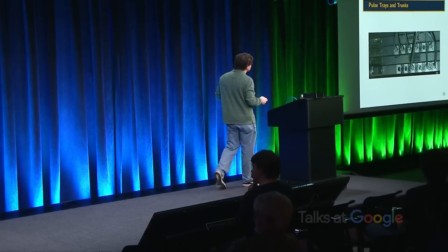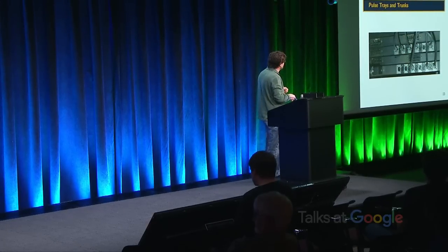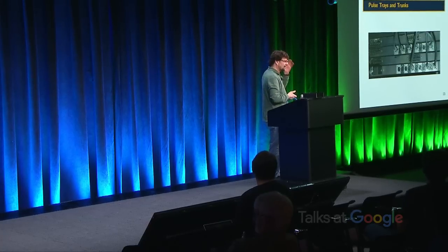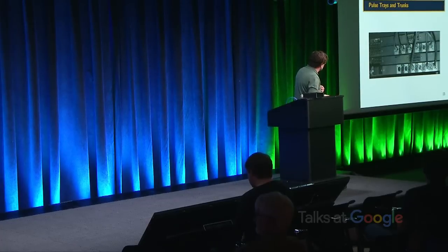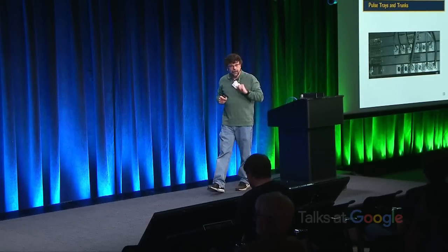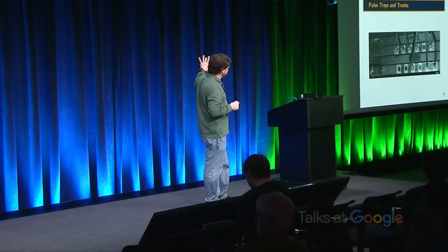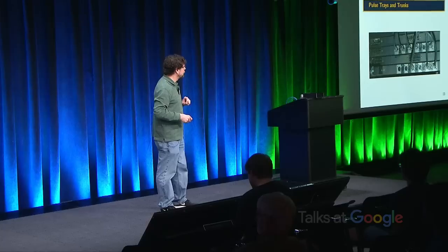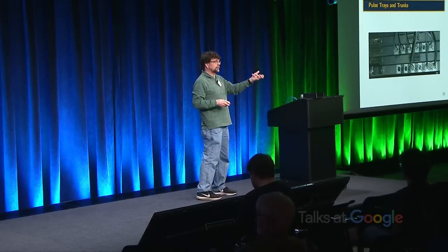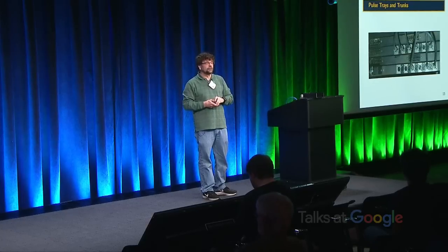And one of the things that is kind of inaccurate is the mixing of these different types of trays. In practice, the ones with these individual connectors, the ones that have the alternating black and white backgrounds, those would run across the tops of the control panels. Sorry, take that back. Those run across the bottom of the machine. The other ones with these multi-pin connectors would run across the tops of the control panels. The multi-pin connector ones were where you carry data, and then the ones with individual pins like these were where you carried control signals.